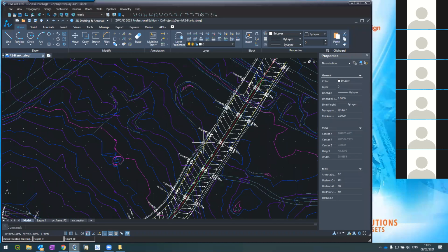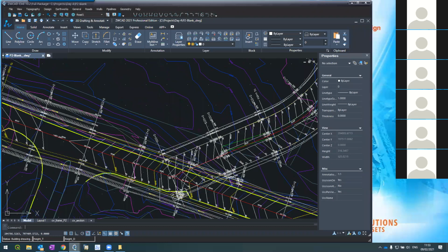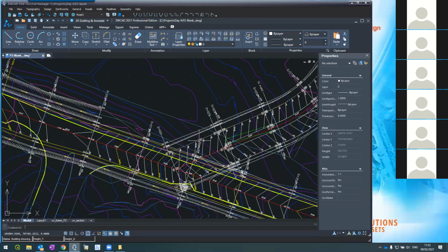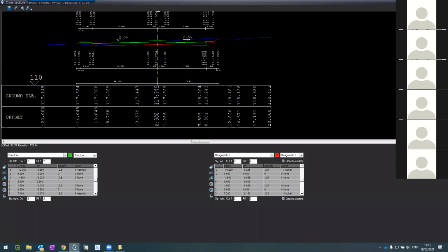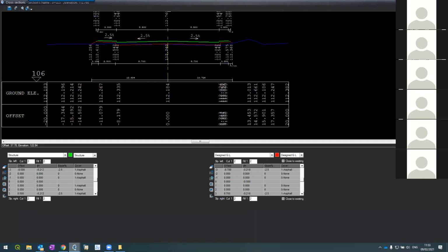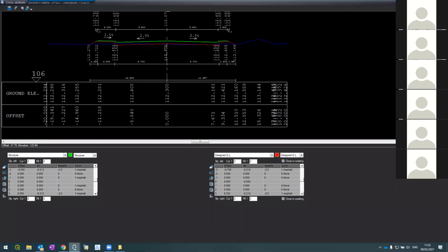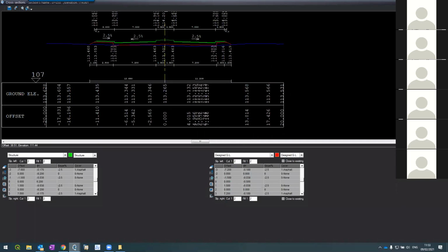The concept. By the way, if it's too complicated for you to create another median, you can create additional sections here manually. We saw how to do it. Just for your example, I want to create a section here. I'm standing at 0 plus 27, press enter, a new section. Not here, sorry. This one, I want to delete it. I use the eraser. Here, I create, I'll call it 0 plus 030.